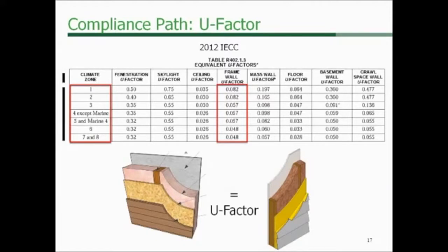So what this basically says is, look, if I have two different walls, this is my base wall, and say I'm using insulated siding or whatever it is, as long as it's equivalent, it's okay. It's the energy performance. Okay, as long as it has the same U factor, I'm okay.